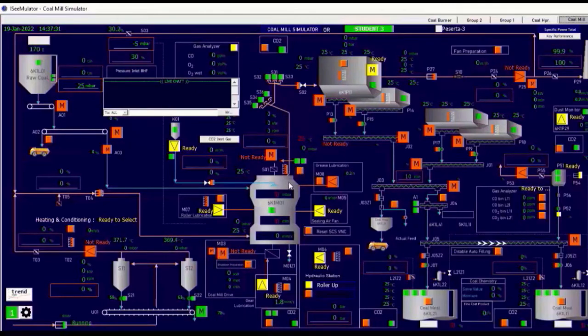Hot gas from the mill rises to the dust collector, and in this dust collector there is a separation between hot gas and fine coal product material. Clean hot gas exits through the chimney, and some is fed back into the mill system as circulating air.